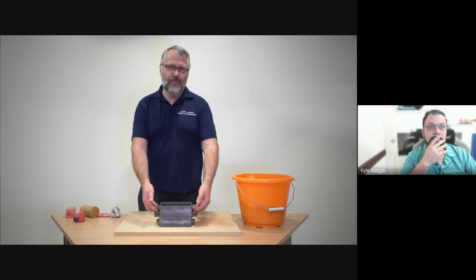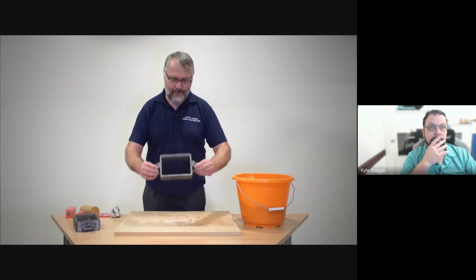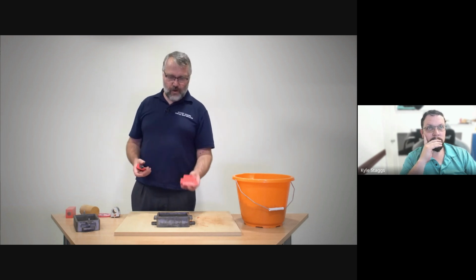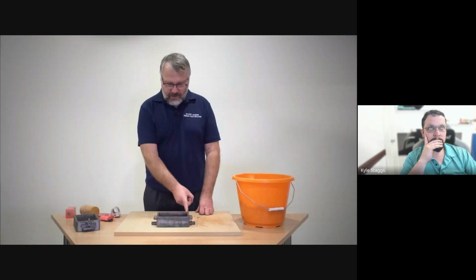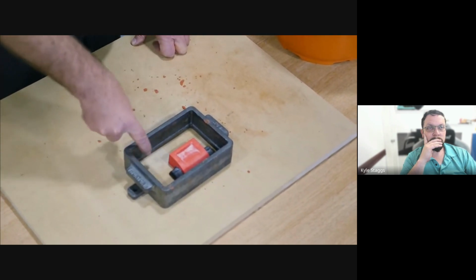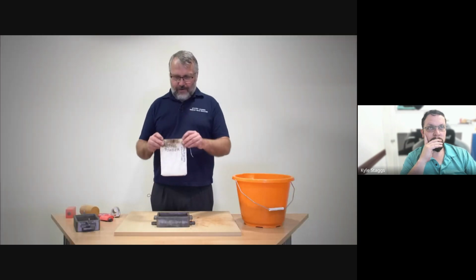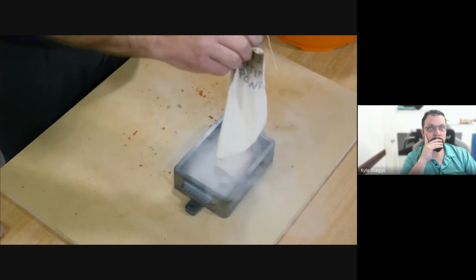So if we take the cope off the top of the flask and set that to one side and turn over the drag, we often refer to that as an inverted drag, and add the first part of the pattern. One side has locating pins, so it sits flat. We'll use the side with the holes face down in the moulding box. This has been set so that nothing touches the sides of the moulding box, and there's a space in the corner for us to complete the moulding work. We give a quick sprinkle of parting powder, and it's just used to help remove the pattern from the sand when we're opening the mould.